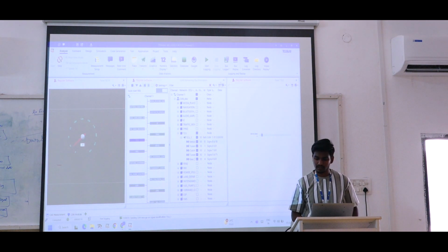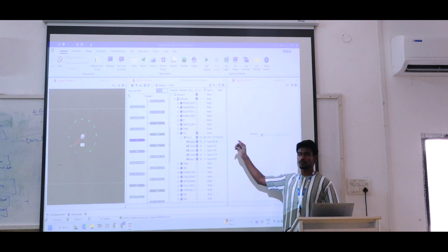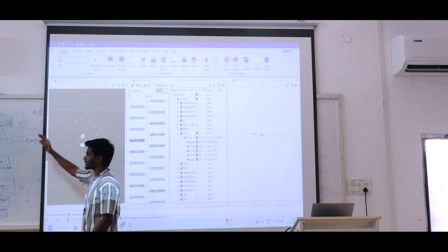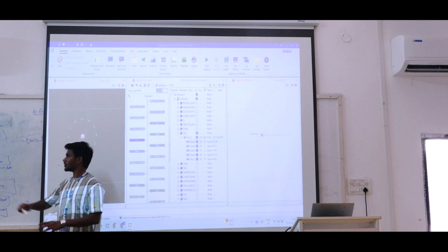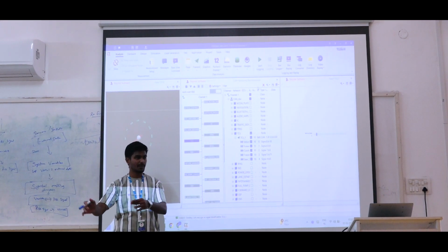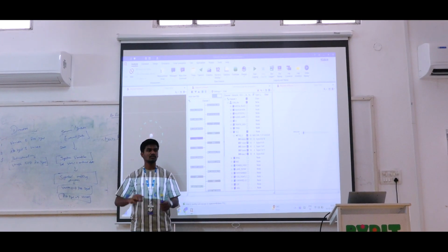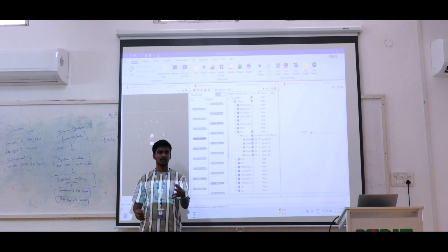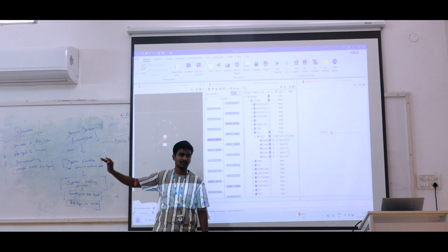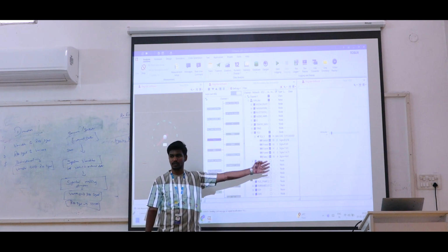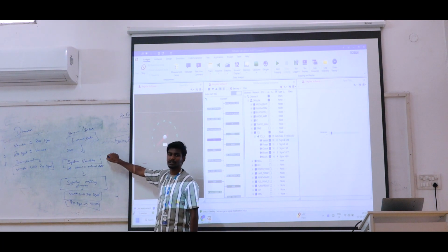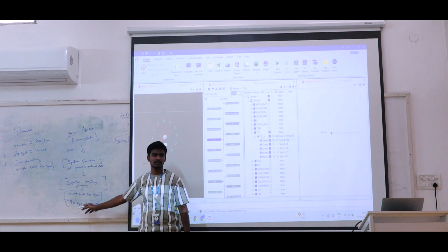Next one is the rest bus simulation. One more input source for the RBS, which means we are able to set the values, is called external data. Using this external data, we are able to get some values from the sensors, digital inputs or analog inputs. What are the values we require? We can take the help of different kinds of sensors. Those values we will get from external sources, and we use the same for the rest bus simulation. That is the concept of the system variables. The system variable acts as an intermediate between the external data and our RBS simulation.